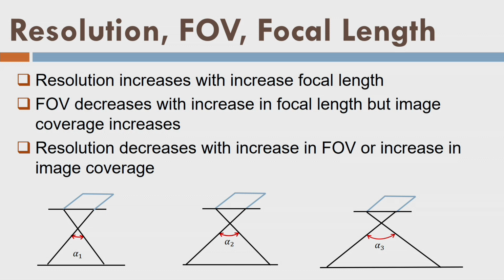And you can understand it by simple logic. If I increase the focal length, the field of view will be less, and as a result this length on the ground surface is less acquired by the camera. Now I have a 12 megapixel camera, so 12 megapixels are acquiring this much of space. Let us see this tablet, for example. Now I increase the focal length, and I can see that the space on this tablet will be less, only from this to this will be acquired.